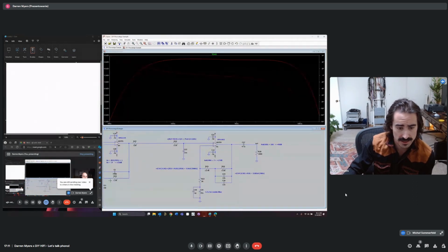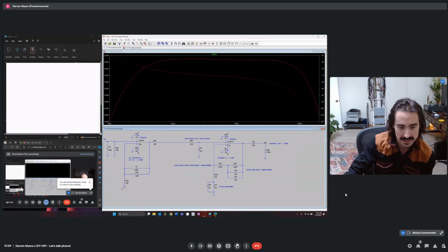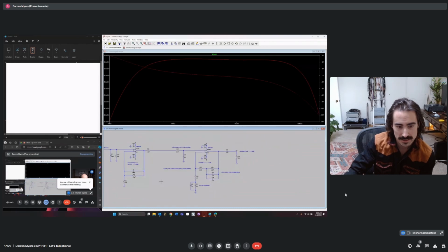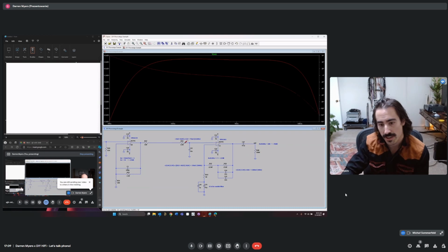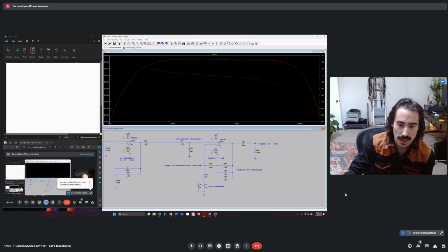It's really this that the amplifier is seeing. Yeah. Also, I think it's pretty important to say that R27 and R24 do not load the opamp because they go into the high impedance node of the next opamp, right? R24 does load U4.